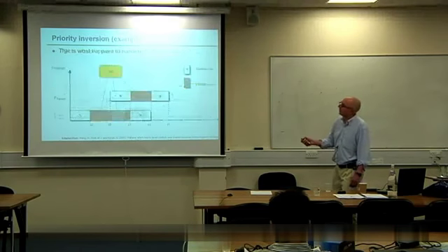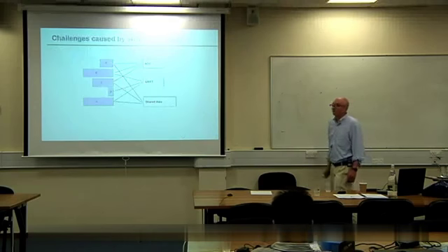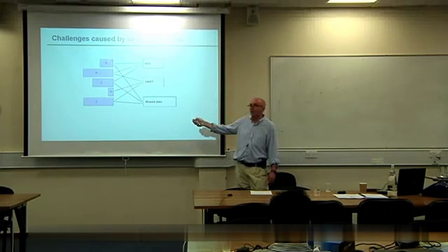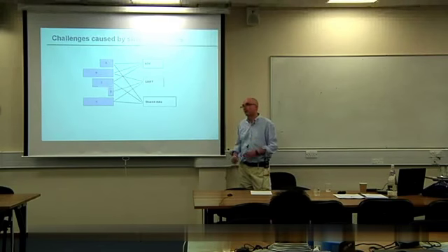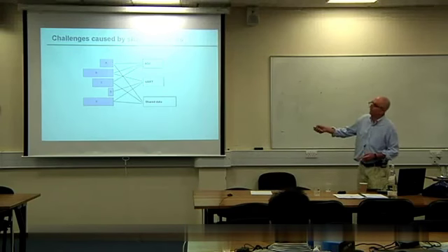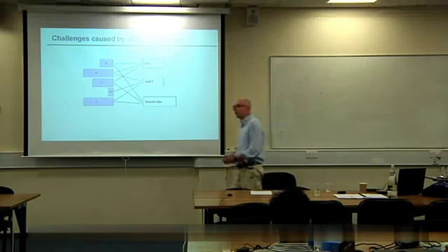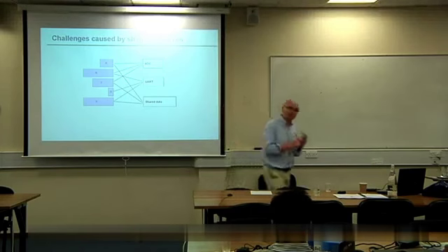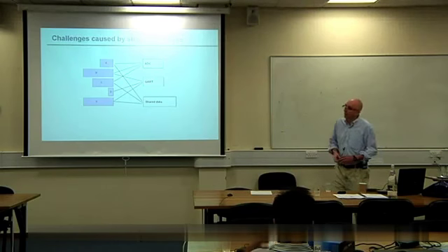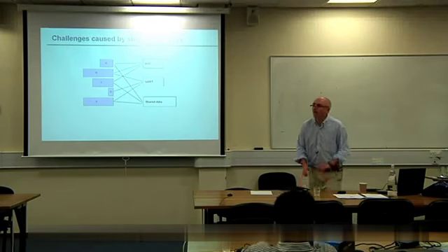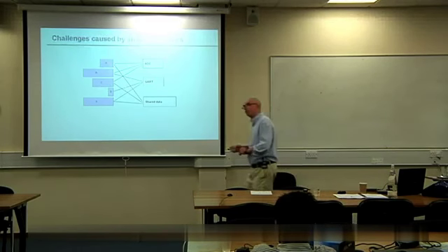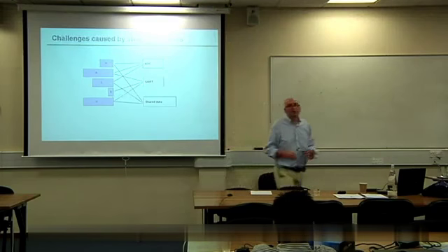Let's just take it back to this. So these tasks can run at any time, and that's the highest priority task. Which task would you make the one, if you had a task that had to take time-critical data from this ADC for your control application, and we're back at your 1 microsecond or so temporal resolution? Do you make the time-critical task the highest priority one or the lowest priority one? Obviously, you make it the highest.